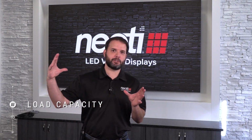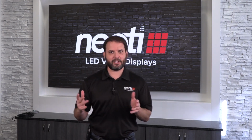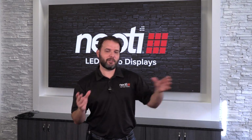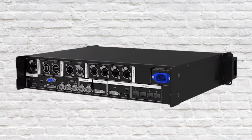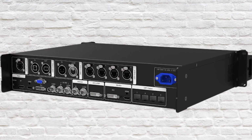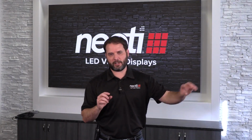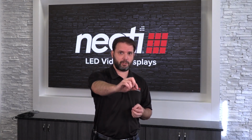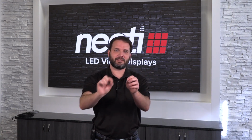When a video signal comes into an LED system, it usually comes into the controller via HDMI, SDI, DVI, some kind of way that the video gets to the controller. From there, it gets to the screen through Ethernet ports, right? And it's usually more than one port available on a controller. Usually they have about 4, sometimes more, sometimes 6, 8, 16, but your typical has at least 4. They go through Ethernet cables, Cat 5, Cat 6, out the port into a panel, and then from there it usually gets chained to other panels in the screen.